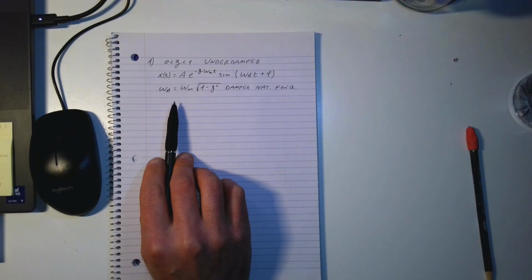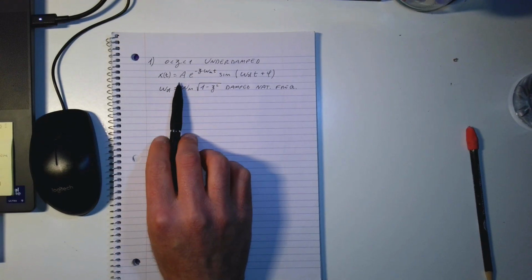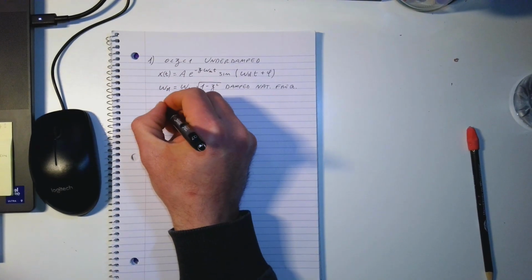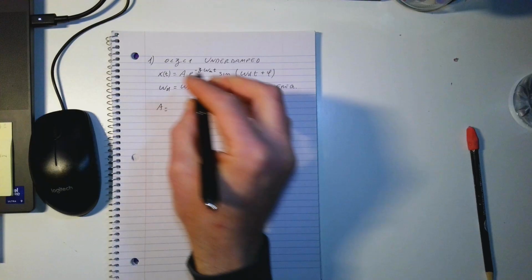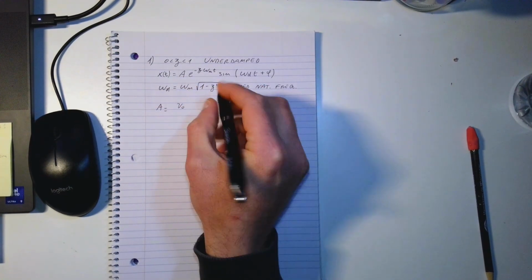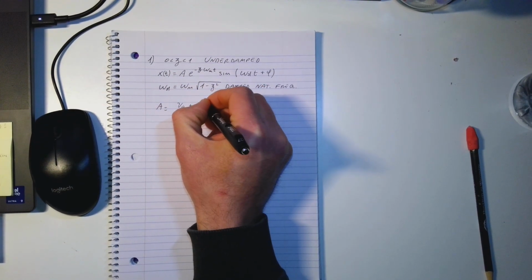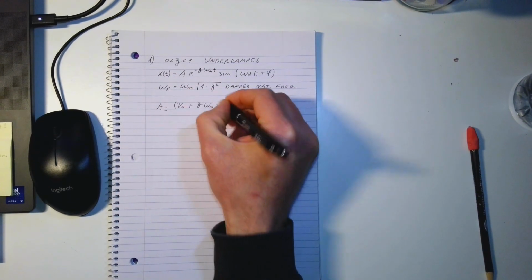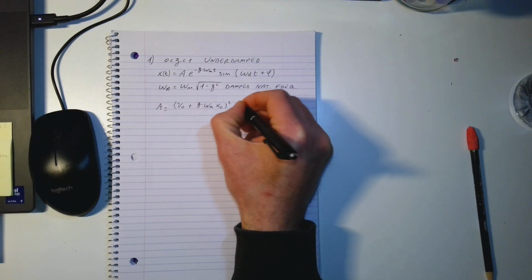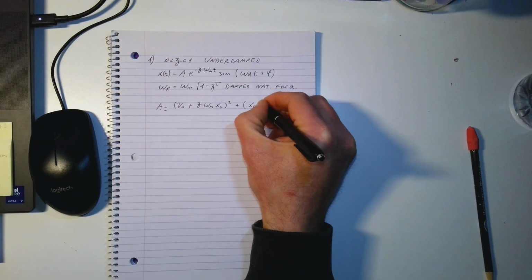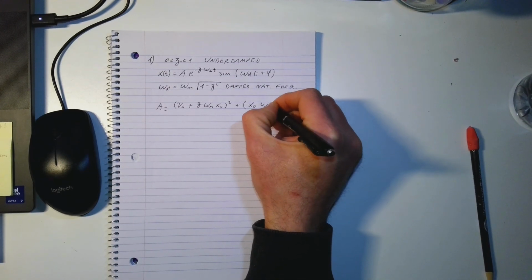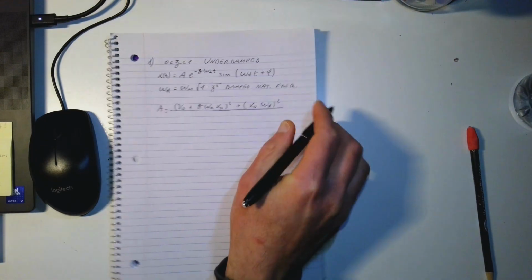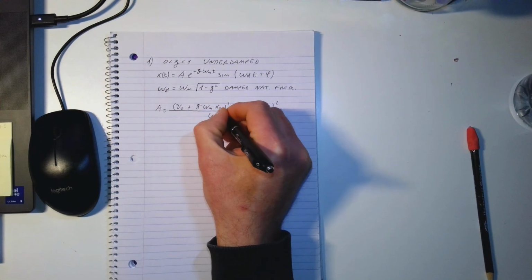We can also write the expression of amplitude and phase for this case. So we have that the amplitude A is equal to the square root of the entire expression: v0 plus zeta omega n x0, squared, plus x0 omega d, also squared, divided by omega d squared.